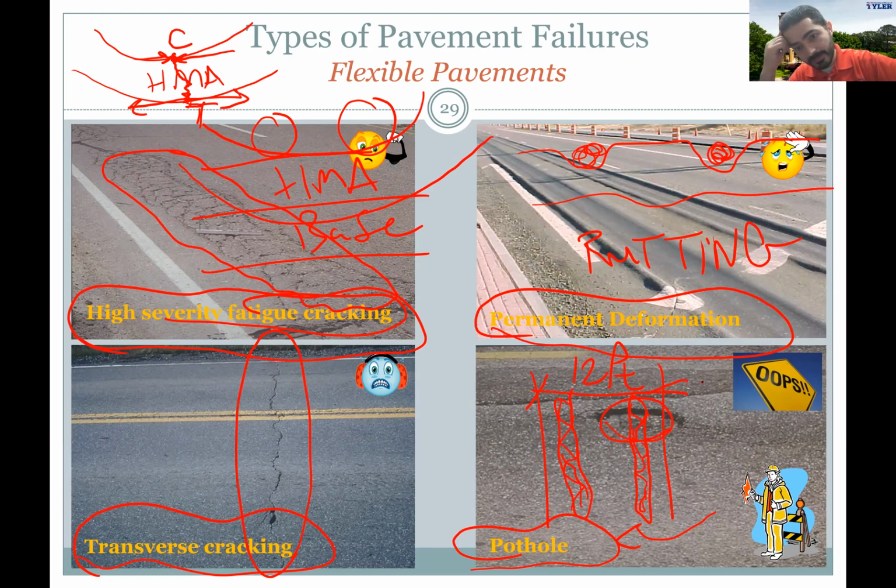Why does this happen? It happens sometimes if we're not paving the whole lane in a uniform way. Sometimes the paver, which is the machine we use to pave roadways, has most of its heavy weight at the major midpoint of the roadway, and the hand of that paver extends all the way to the shoulder or close to the shoulder. As you could see, this is the line of the shoulder here, and there is not much weight towards the end of that location here.